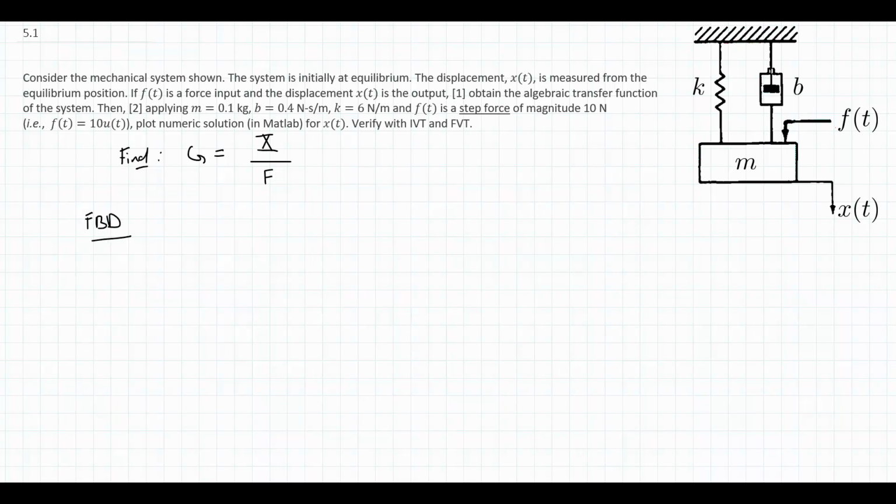In this case, there is only one object that we need to draw the free body diagram of, and that will be the mass. So on our left-hand side, I'm going to draw all of the forces that are affecting this mass. We are given the coordinate system of x positive down here, and that's what we'll be staying with. I'm not going to rewrite the coordinate system since one was given to us, but there'll be nothing wrong with establishing x positive up, driving everything that way.